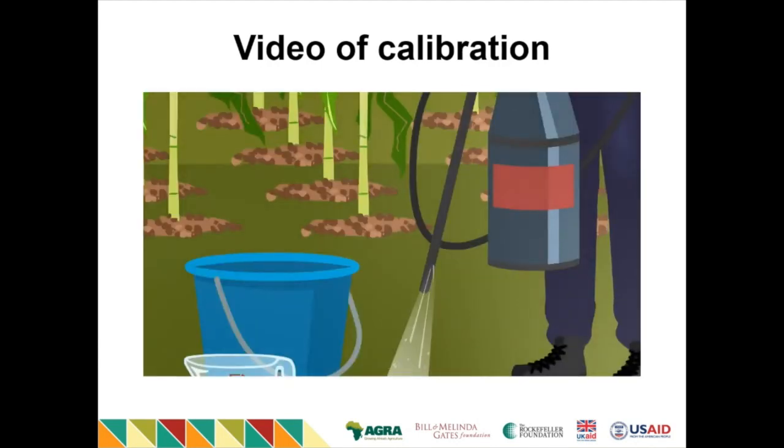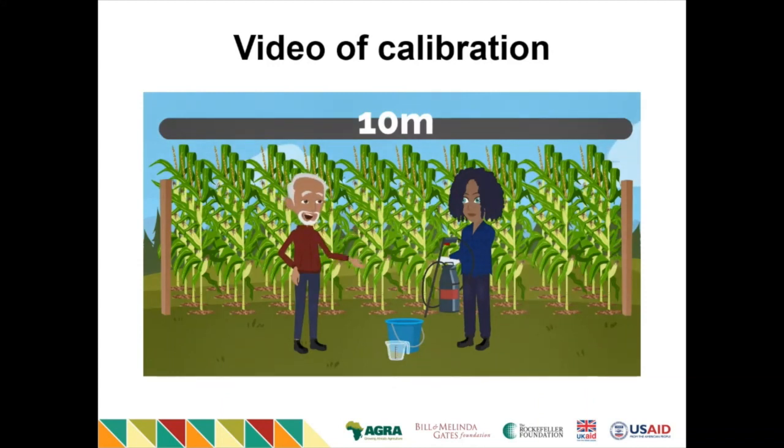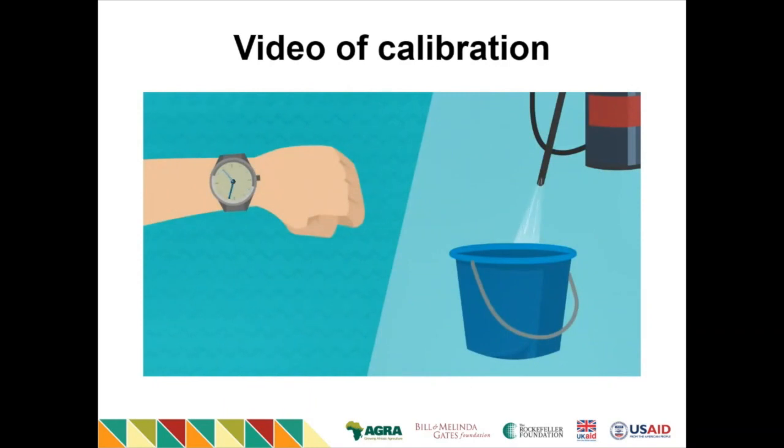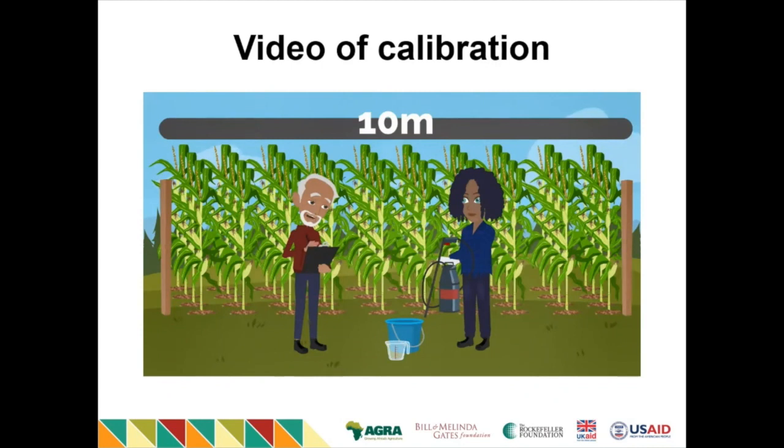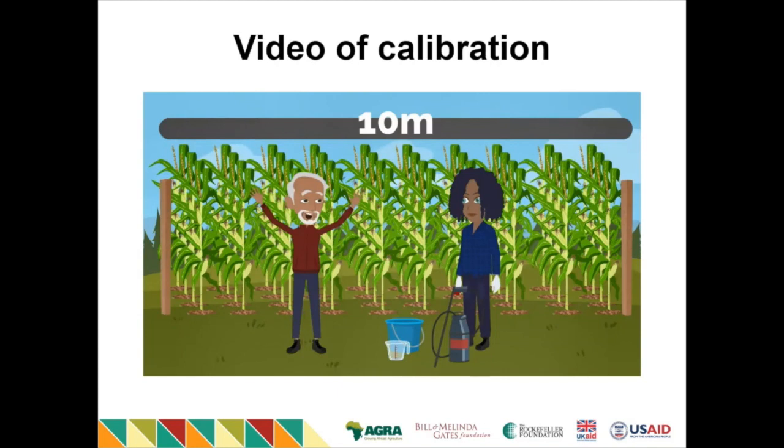Spray into the bucket now and I'll start the 30-second timing immediately. When 30 seconds is up, you must move the nozzle away from the bucket. 27, 28, 29, 30. Great. Right on time. So what now? You can carefully pour the water in this bucket into the measuring jug and I'll record the volume. This spray, measure and record process has to be done 4 times. We'll have to repeat this 3 more times so we have 4 readings and we can work out an average.